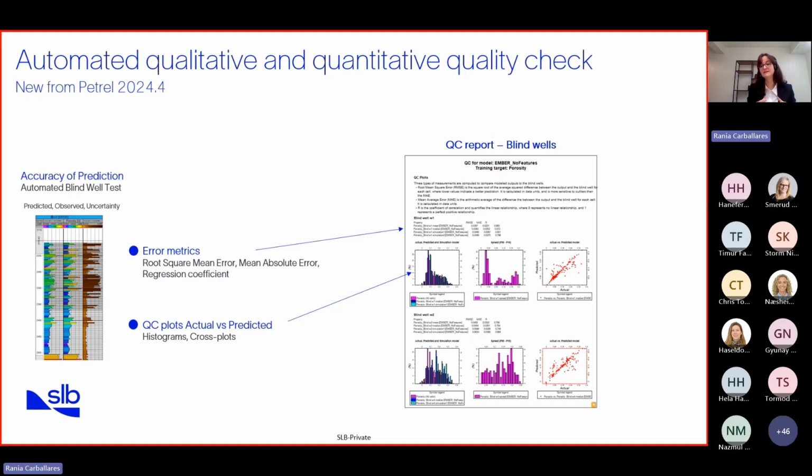With a blind well test, you perform a quality check excluding a number of wells, or one well, from the estimation, and then you QC the estimation accordingly based on excluding those wells. So you can QC the predictivity of the blind wells using a well section window with a predefined template, and that will also be created automatically, gathering all the information in the QC report.